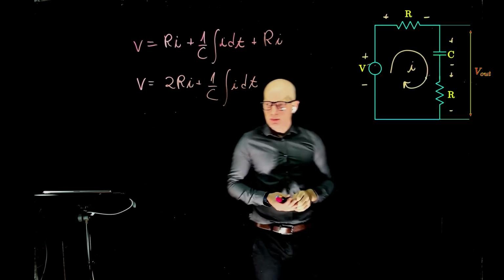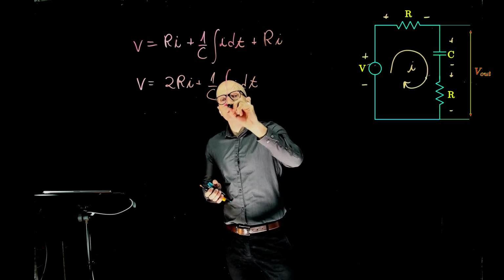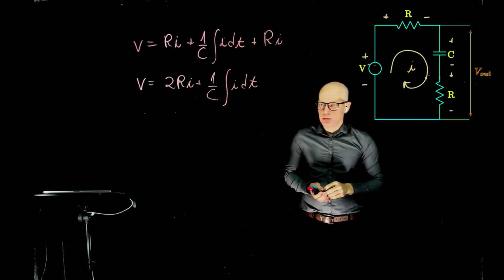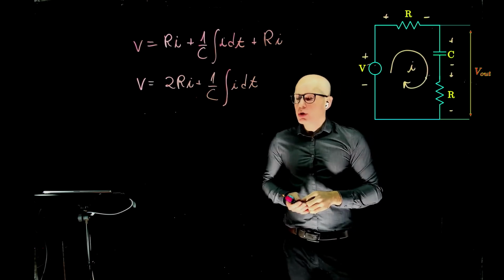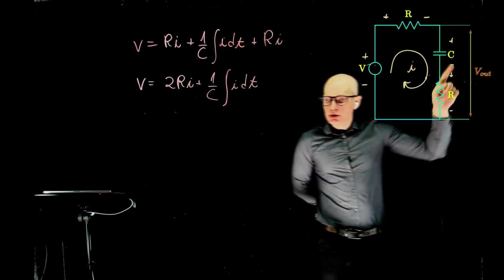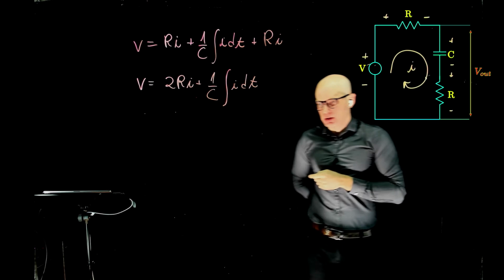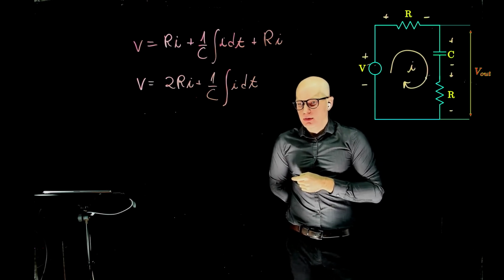Professor, just one simple question. For this case, can we consider their relationship as the voltage divider? You could, yeah, you could do a voltage divider for sure. The only issue is the capacitance here, so your voltage divider will end up with an integral. Okay, I see. Thank you.